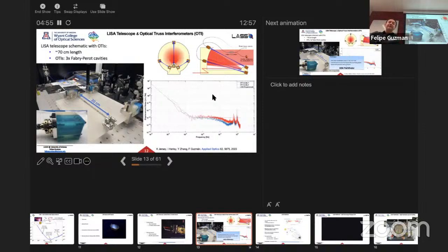Well, it'll be basically similar restrictions and issues that you would have with the telescope itself. The way we designed the optical truss, as you see here, this is just blue tape, by the way, protecting the surfaces, because these are polished surfaces, so you can do hydroxide catalysis bonding to the structure itself. The telescope is being fabricated out of Zerodur, and so are these pieces here. They're Zerodur, so you can just do bonding straight into the system. So all of that, yeah, temperature would couple for sure.